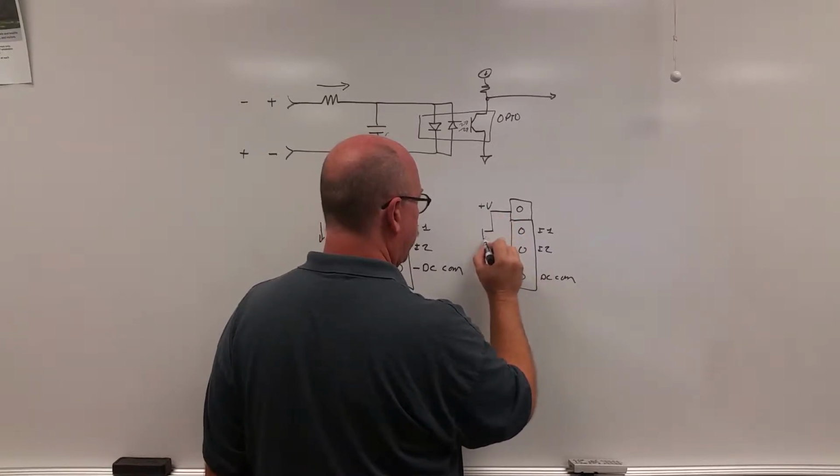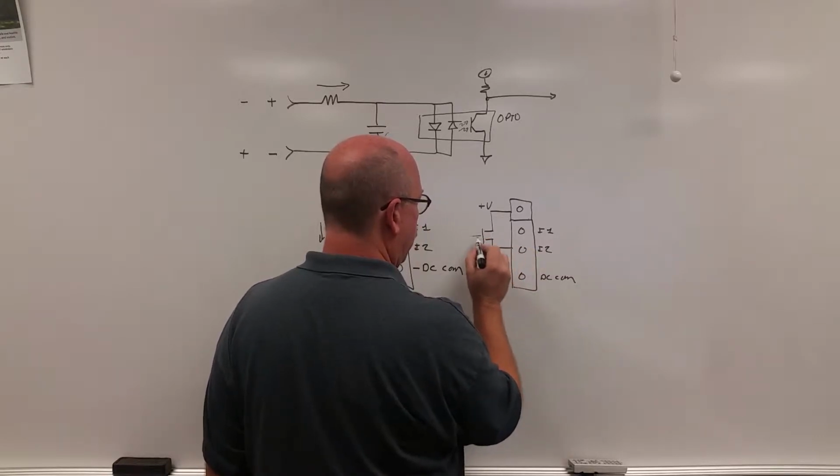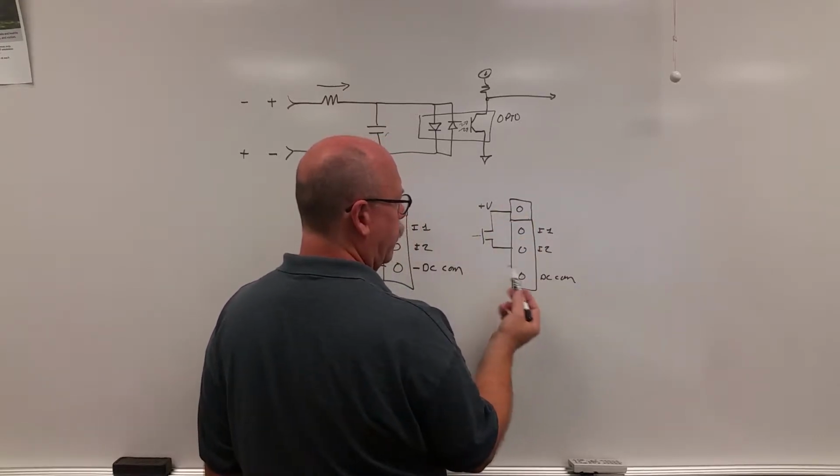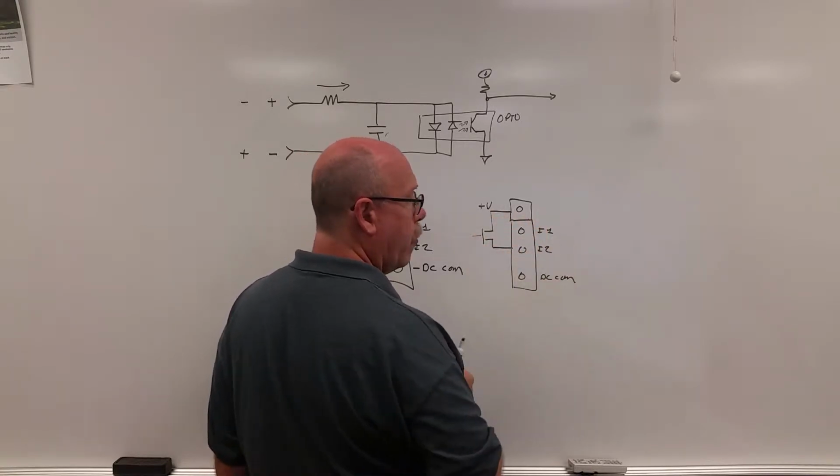I'll place a switch here. I'll pick up the same input 2. Here I'm sourcing the input, which means I'm applying a voltage to terminal I2.